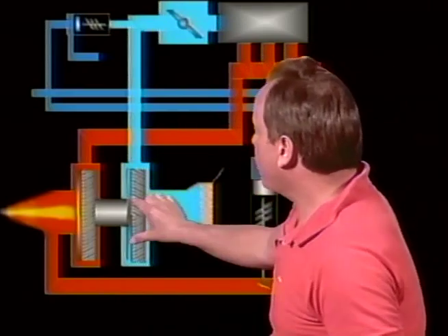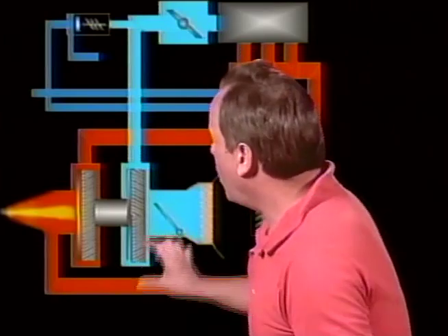So when you switch from low impeller to high impeller in a supercharger on the ground during a ground check, you'll have an increase in RPM and an increase in manifold pressure. And just to confuse you a little bit, they'll ask you about this: you'll also have a momentary drop in oil pressure because oil pressure is used to switch from low impeller to high impeller. That's it. That's the big question they ask you on the test about superchargers right there.